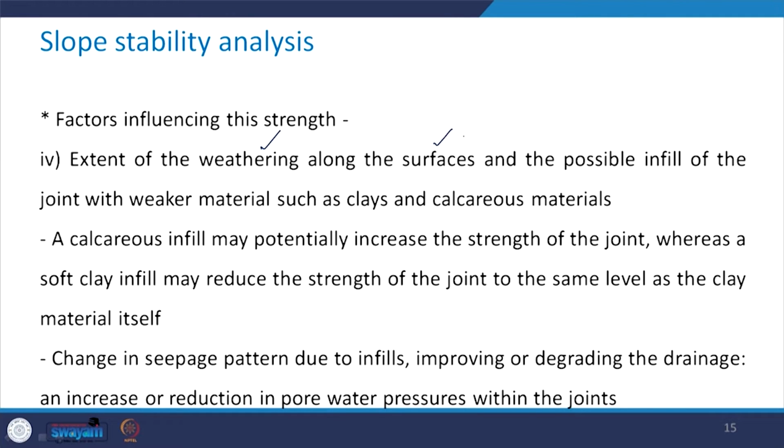In case the infill is a calcareous one, it may potentially increase the strength of the joint, whereas in case of soft clay as infill, the strength of the joint will be reduced to the same level as the clay material itself, because it will be the soft clay infill which will govern the strength characteristic of the